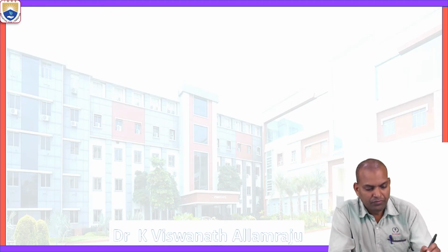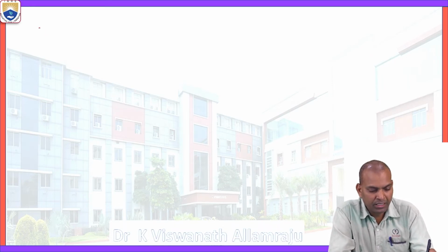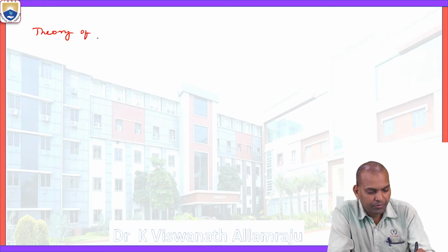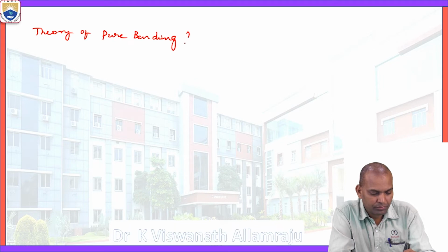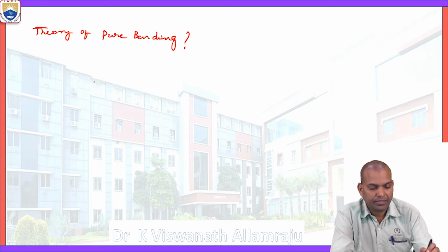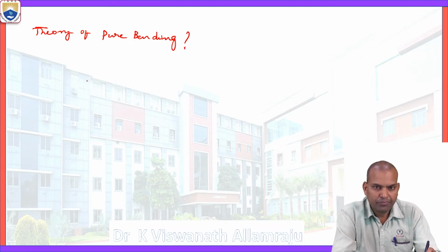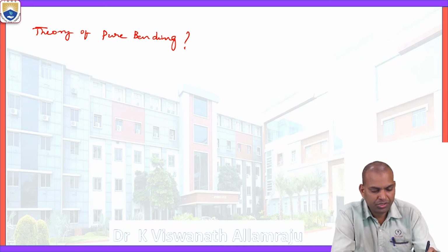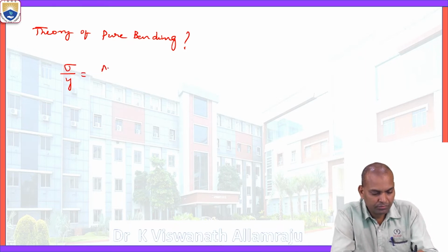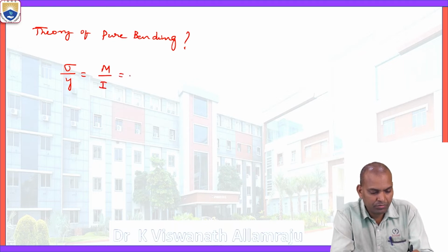In this, what is pure bending? After the pure bending concept, what is the theory of pure bending? Theory of pure bending, mathematically, is sigma by y equal to M by I equal to E by R.